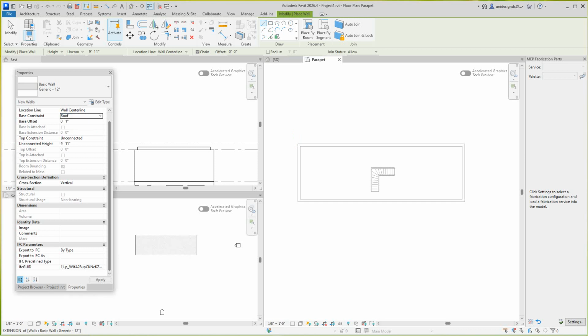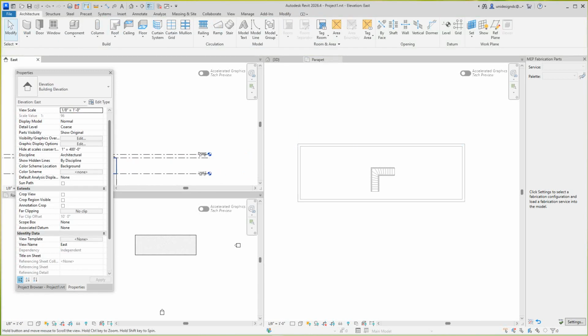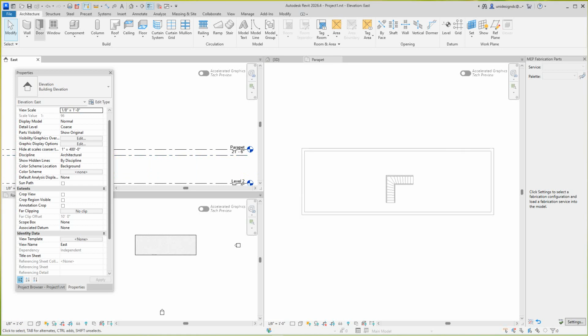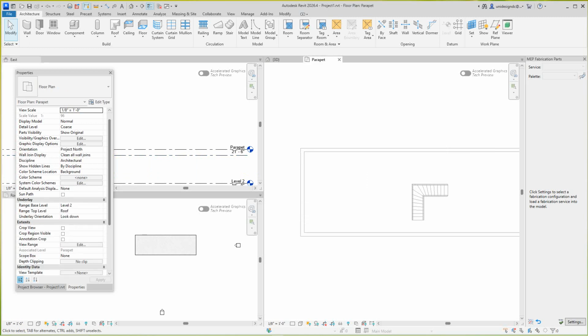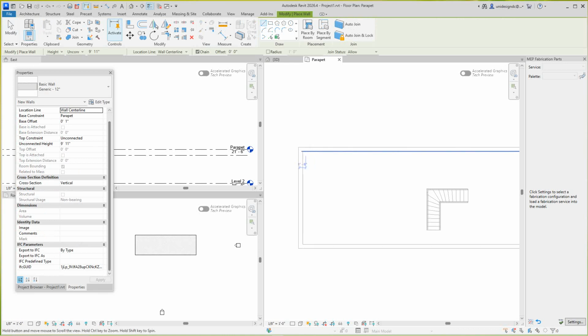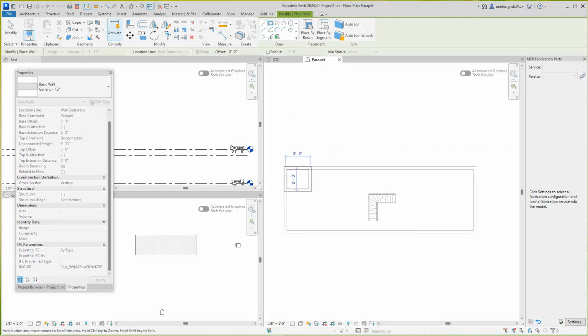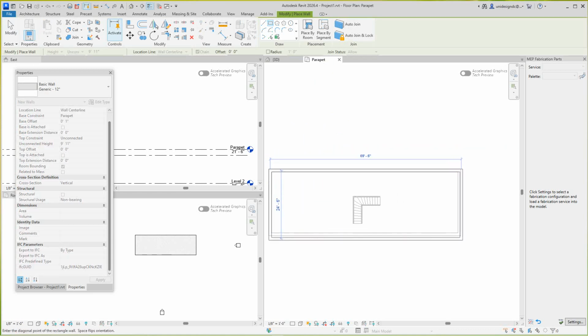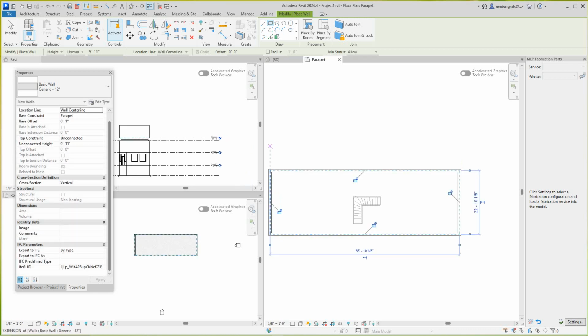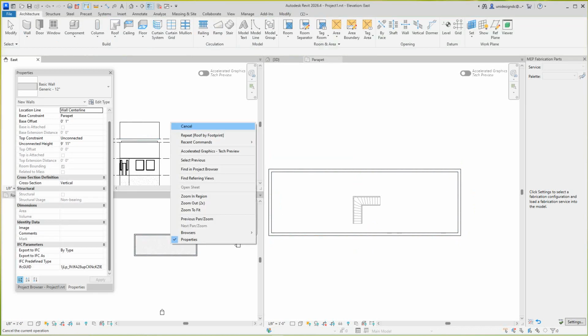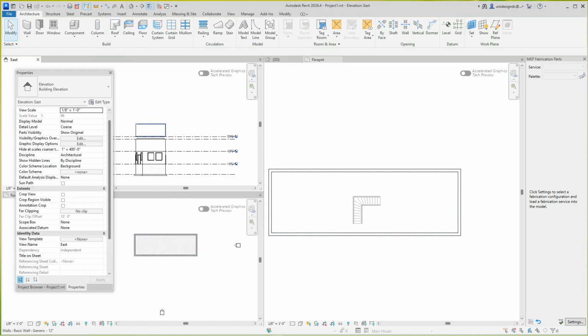The height is going to be, where we got height, it's the parapet. So here, let's go with this wall. We can change that later on, but let's just get the wall in here now while we got it selected. So I'm going to go with my wall here, 12-inch basic, and I'm going to go from here. Let's just do a shape, say here through to here. And now we've got this going, so we can collect this wall now.